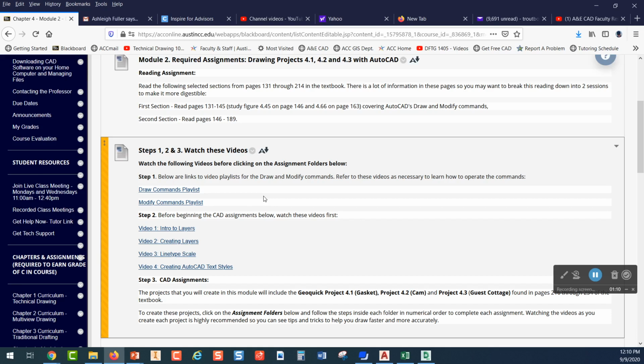And it starts by drawing a rectangle that's 18 feet by 15 feet, and then using the offset command to offset that 4 inches to the inside, because the walls are 4 inches thick. Okay. Then you're going to explode both of those rectangles, and you're going to use the offset and trim command. As you can see on page 228, near the bottom of the page, you're going to offset lines. And then you're going to offset them 4 inches for the wall thickness. Then you're going to trim those out to start making the bathroom and the closet. Okay, so you're going to get really good at using offset and trim, and you need to be good at that. And so the videos, again, I would watch the video when you do this.